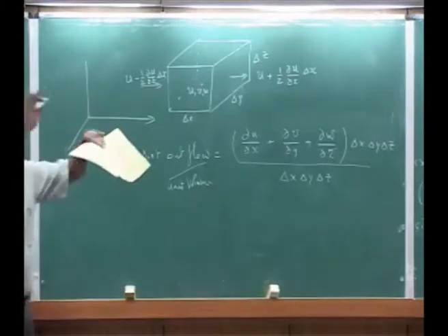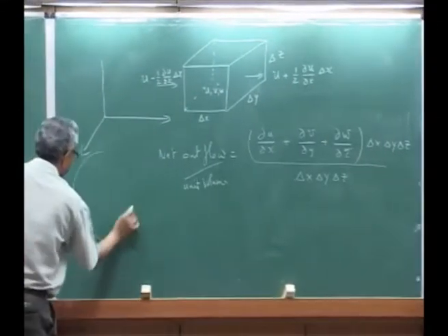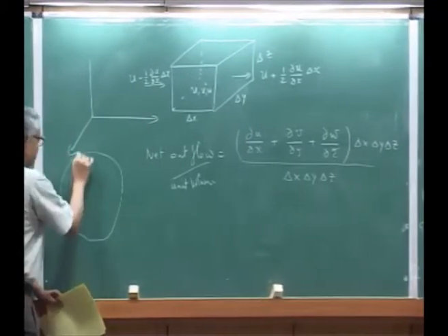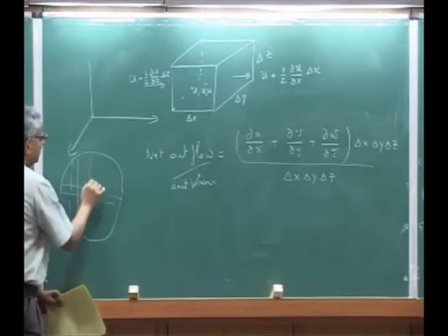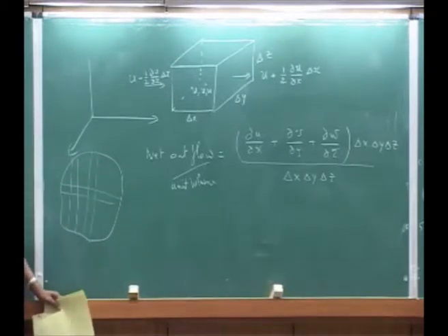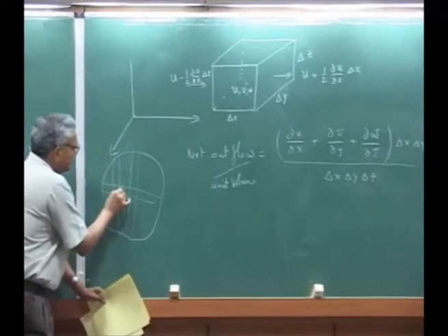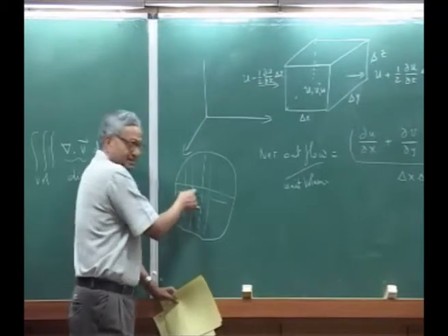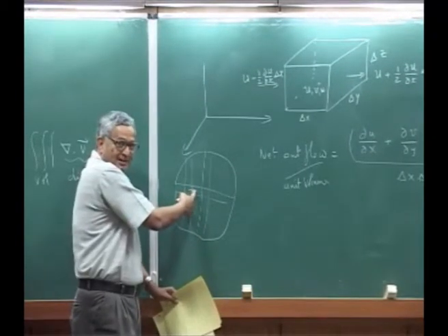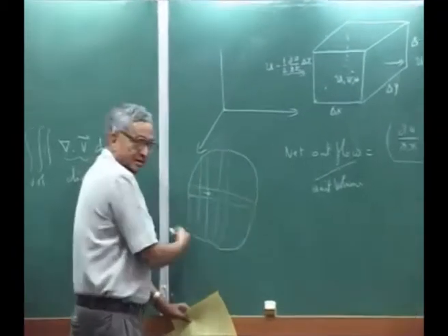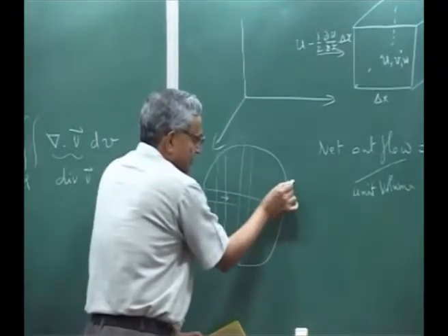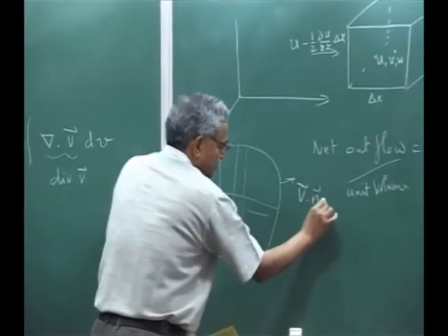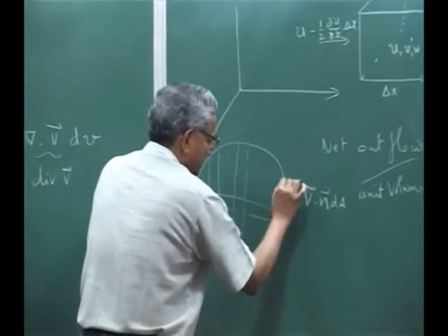Now if you assume some control volume, and you divide this into several blocks, small blocks in the 3D. Okay, so whatever is coming in here for this cube, whatever is going out, that is nothing but what is coming in into the next element. So like that, if you keep the whole thing, finally this will become V dot N dA, where dA is the small elemental area.